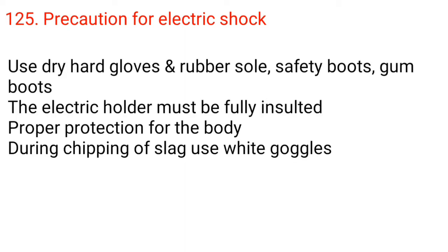125. Precaution for electric shock. Use dry hand gloves and rubber sole safety boots, gumboots. The electric holder must be fully insulated. Proper protection for the body. During chipping of slag, use white goggles.